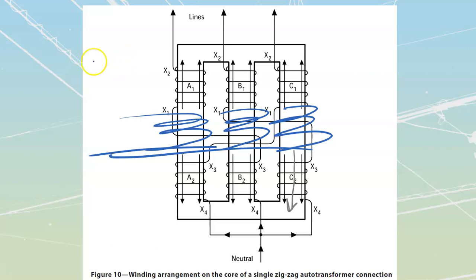And so you are just going to get a KVA spec, and the transformer is going to come with A, B and C labeled on it, as well as a big N, and you're going to make those connections as is. So don't stress too much about this one. A lot of people get real hung up on the zigzag because they go, but that thing, I don't get it. Why is it doing the thing that it's doing? Well, it's doing it because it's straight up electrical theory, but it's not something that you need to understand the inside of. You have to be able to describe it.